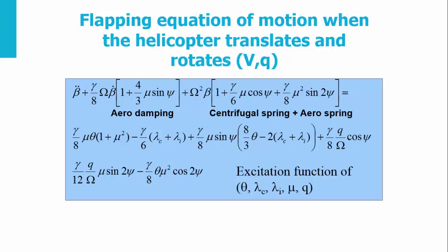You see that this excitation is a function of the pitch angle, the perpendicular component of the forward velocity on the control plane, induced velocity, advance ratio, and pitch rate. And you see also that this excitation is exciting at the natural frequency of the blade, omega.